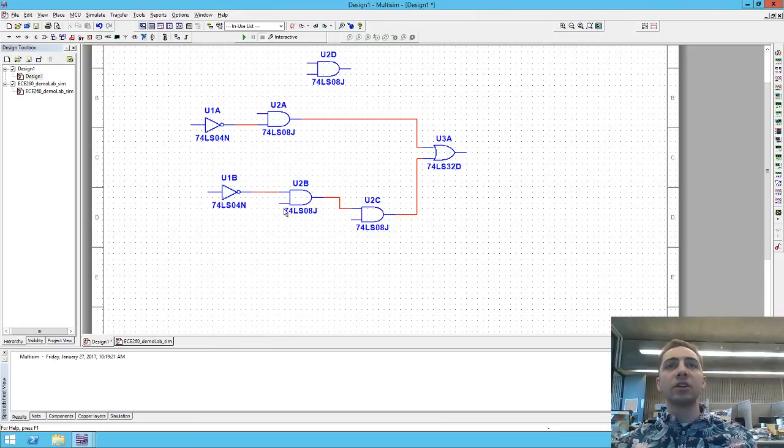Now this is much closer to what we had in the original schematic that we drew in OpenBoard with a pen. It looks much more similar. It still is the same situation. You'll notice that each of these is labeled as A, B, or A, B, C, D, and so on and so forth. The next thing we're going to do is we're going to place on-page connectors.